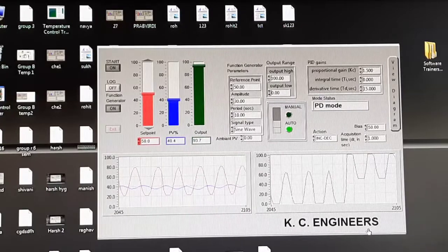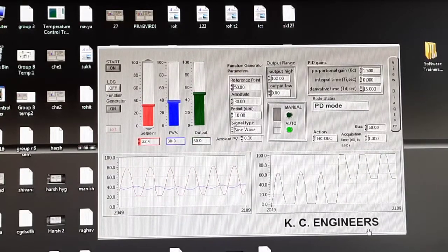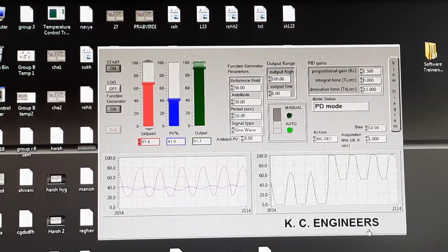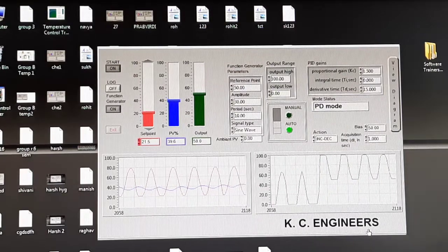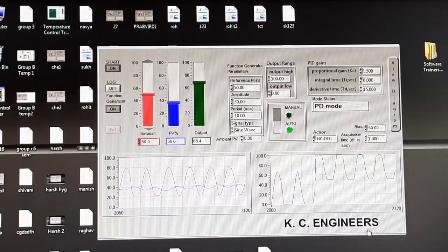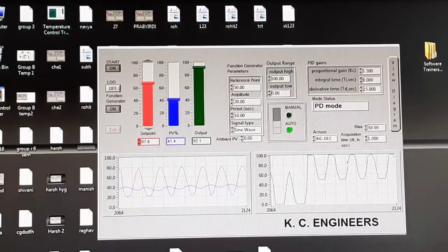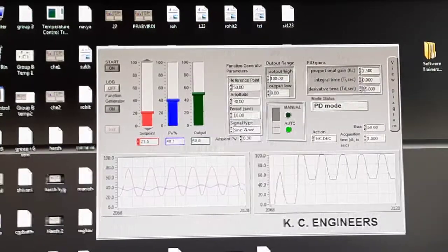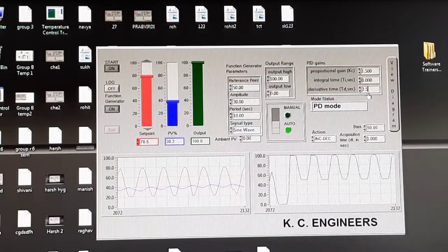So let the system come to the steady state, and if you are getting smooth curves, then that means the error is minimized, so that we can finalize the derivative data. Somewhat smooth curves you are getting, but the green one is not a sinusoidal curve. You can make it more smooth. Again here also you will decrease to half of the initial value, that means 7.5.